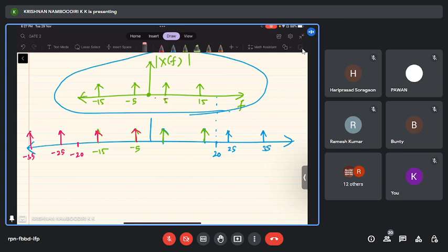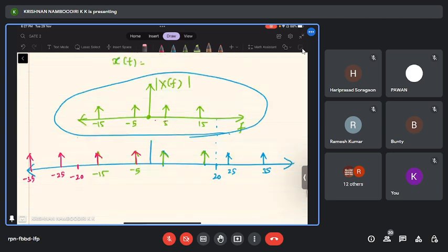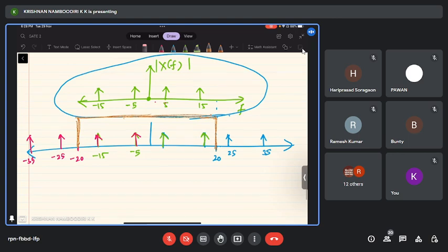So again, the magnitude will get doubled, right? Other than that, the things will look exactly the same. So now I am applying a filter centered at what frequency? Again at 20 hertz. An ideal low pass filter that will have a frequency response looking like this, right?